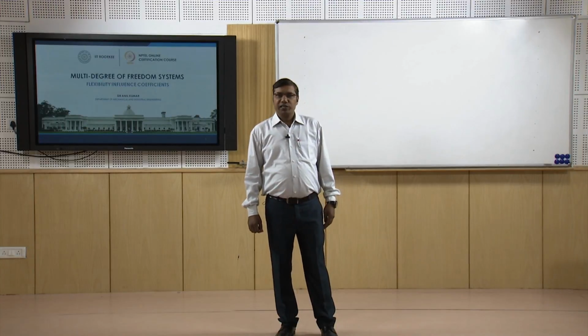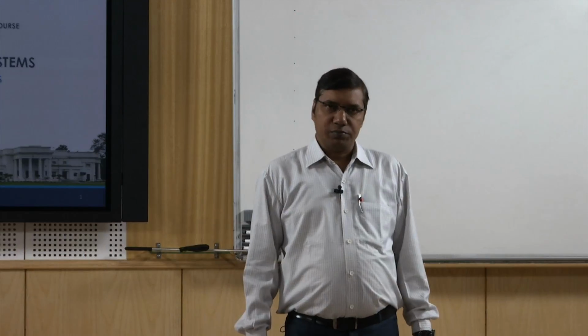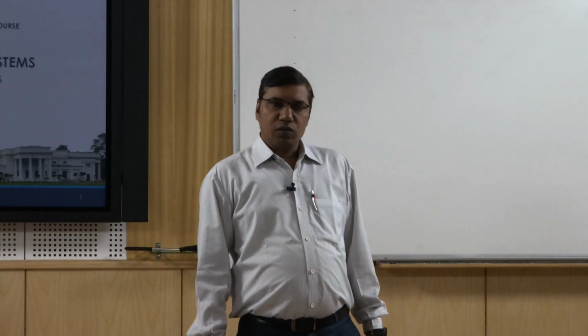So welcome to the lecture on multi-degree of freedom system. We will discuss today the flexibility influence coefficients. So what is flexibility? Flexibility is the reciprocal of the stiffness. And we know that in any vibrating system we have mainly three elements: spring, mass and damper system.